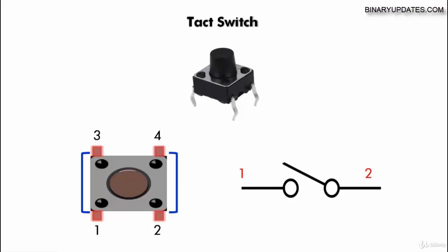The second use is to generate an interrupt. In an embedded system, if you want to generate an external interrupt, then adding a switch to generate that interrupt is a very popular practice, because switches are very handy to add, and when you press the switch, a certain piece of code will run and a certain function will be performed.